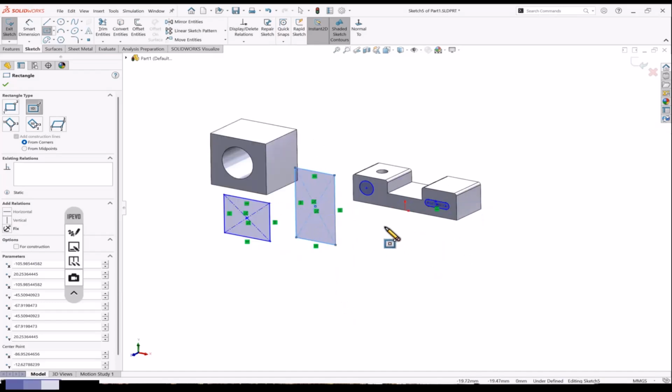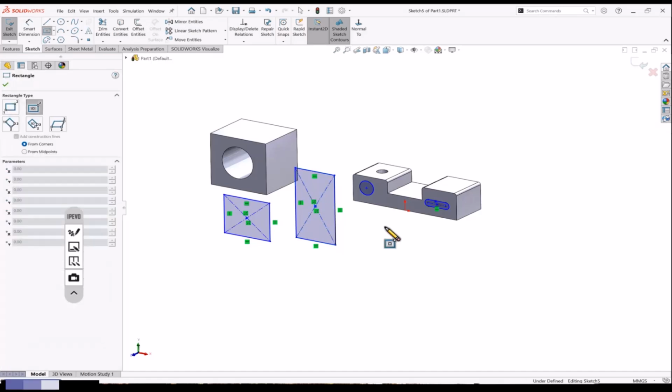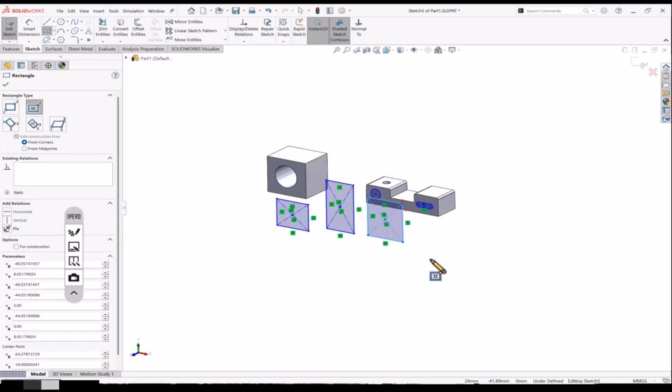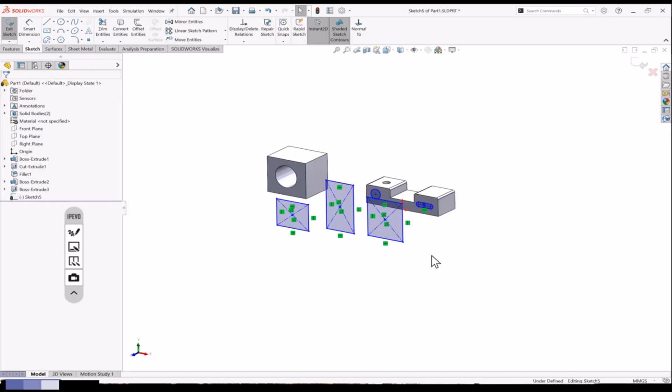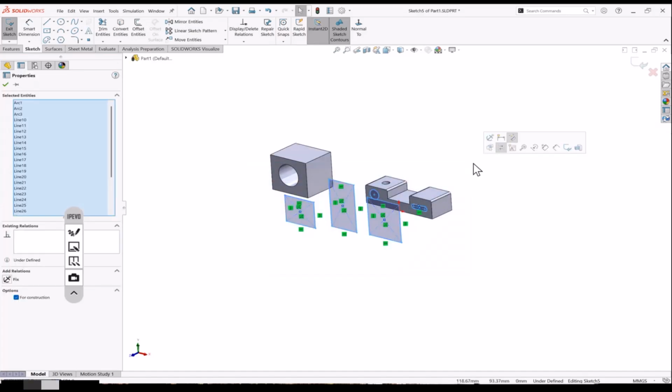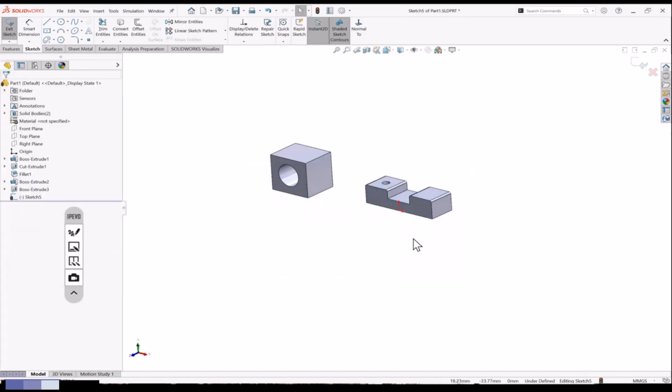If you cancel any command you're using, like again I'm canceling, and I hit the enter button, it will be active again. So the last used command, you can take it again by pressing the enter button. Understood? Same as AutoCAD. By pressing enter, you repeat the command.